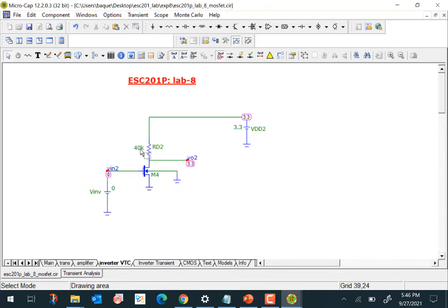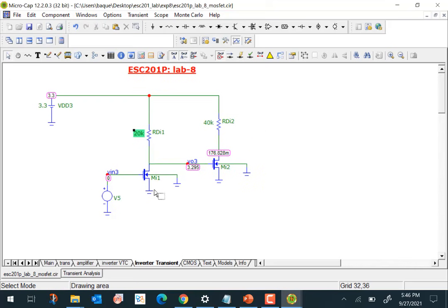So the 0 point here, note, for example, you can see from the voltage transfer characteristics that the value when the output is supposed to be low is no longer a very low value. That rises as you make the value of the resistor smaller. So that's where the trade-offs are in the design of this particular inverter.